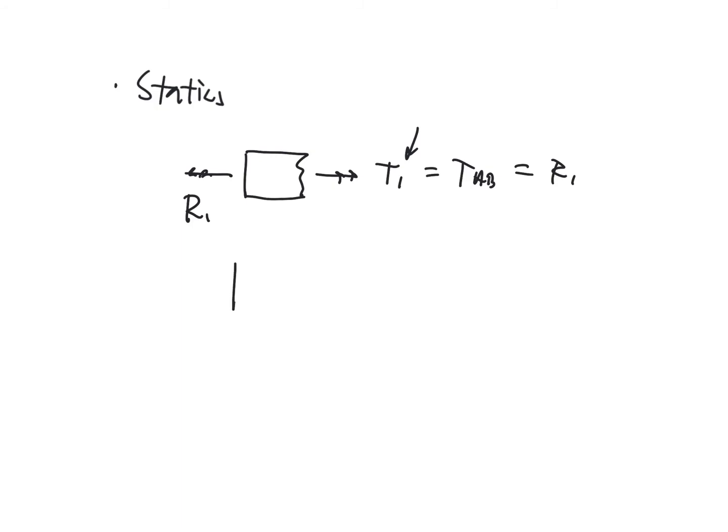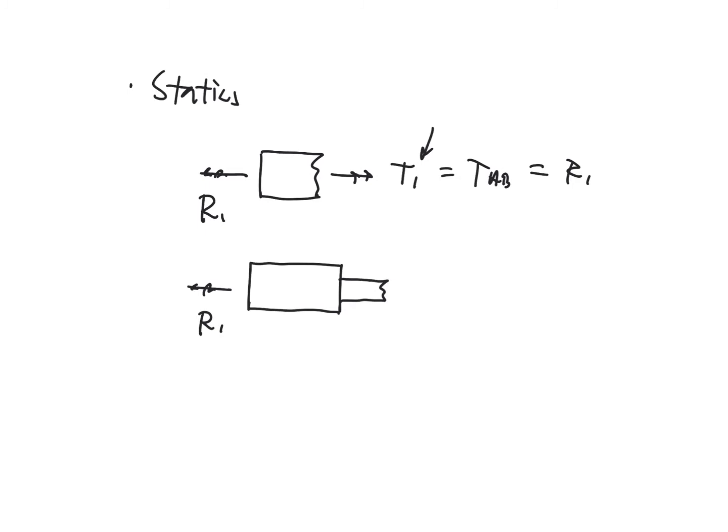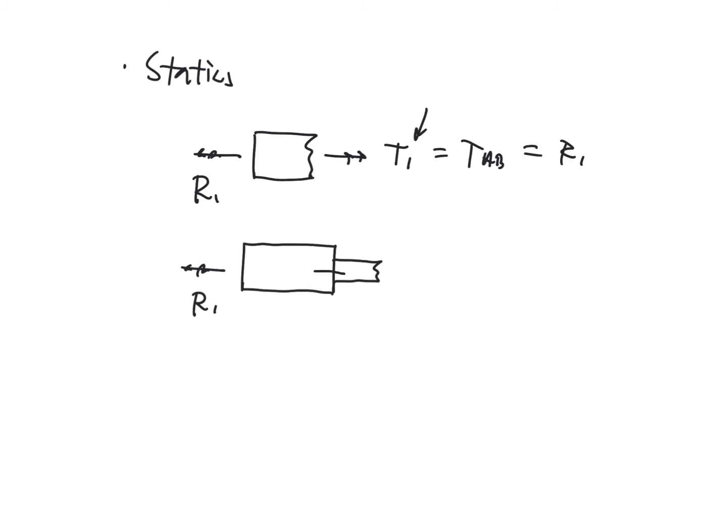Then our second cut, again, we include the entire segment of AB, and then we go into B and C. So we have R1, and here is our torque of 4 going to the left, like so. And then there is our internal torque of torque 2, or if you want, you could call it the torque between B and C. I'm not going to be picky about this, as long as you show me that you understand what those are, that's fine.